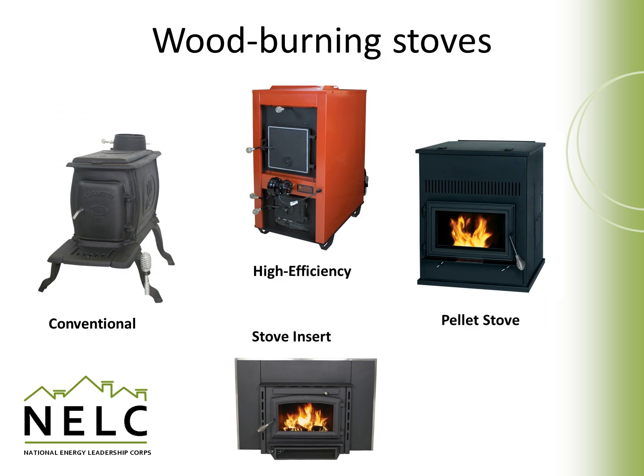Wood stoves have much better overall efficiency, with AFUEs between 63 and 78. Their performance is often dependent on the quality of the stove and the fuel. Conventional wood stoves draft naturally and are not as efficient as pellet stoves. Newer high efficiency stoves use very efficient combustion methods and can reach AFUEs up into the 90s. They require some maintenance, but they save a lot of fuel and they burn very cleanly.